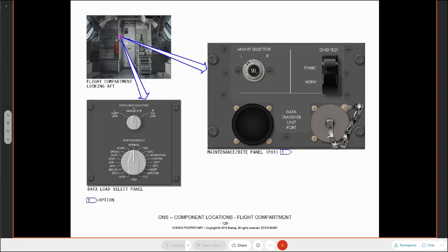The network file server. If you go to your local computer store, get an SD card, 32 gig card, stick it in the front of the network file server, it'll automatically initialize it. Okay, format it to make it compatible with the network file server. But there's nothing obscure about them. They're just a standard SD card. Okay, they are standard on the aircraft. Yes. I'll give you some more information about the SD cards in a moment. Some good information about those as well.